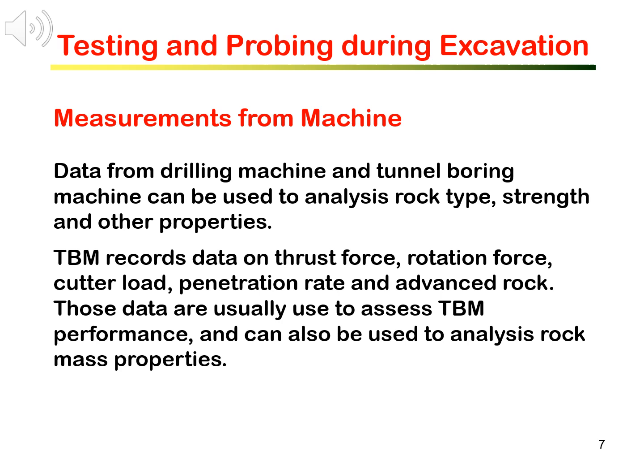Typically, TBM records data on thrust force, rotation speed, rotation force, cutter load, penetration rate, and vibration. Those data are usually used to assess TBM performance. However, those data can also be used to analyze rock mass properties, as machine data is induced from the response to the ground.